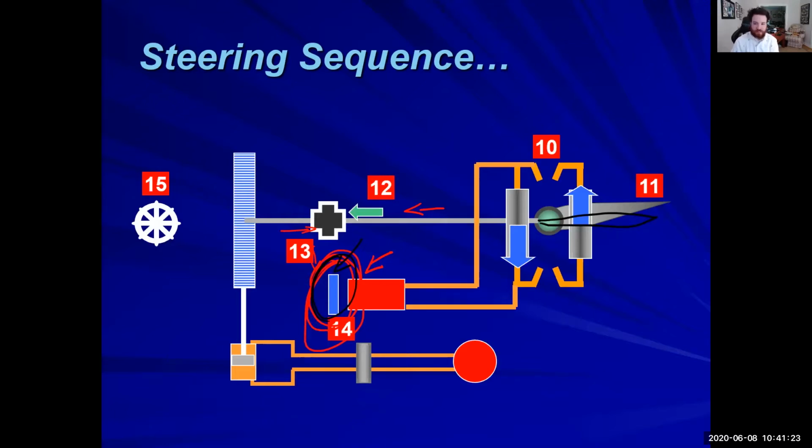All right. So if this rudder moves to starboard and it stops moving, that means that tilt plate has gone to its 0 position. That's all that tilt plate is showing, is that it's done its job and it's locking that rudder into that position. If it's at its 0 stroke, it is happy where that rudder is.